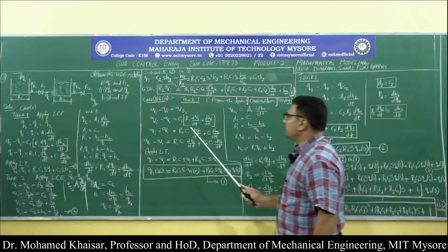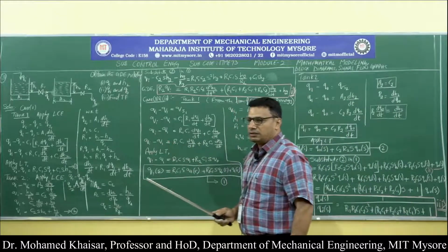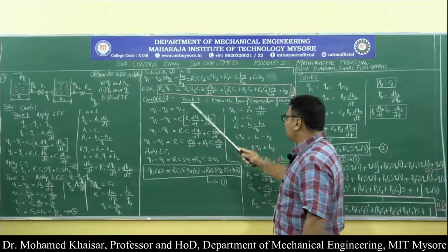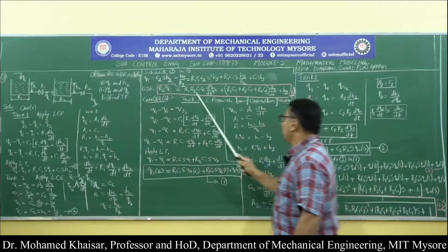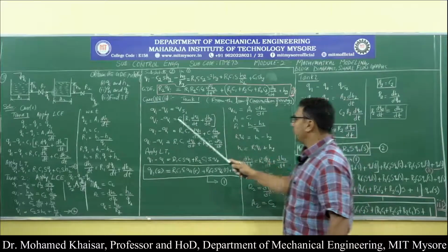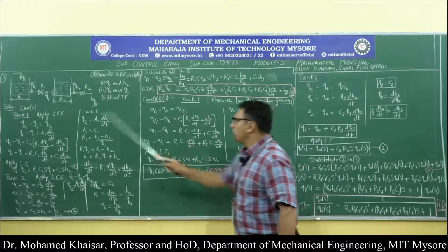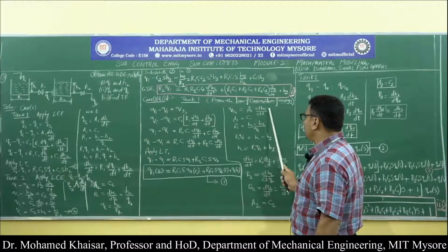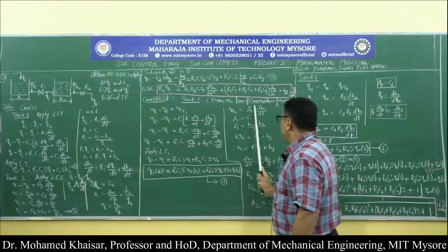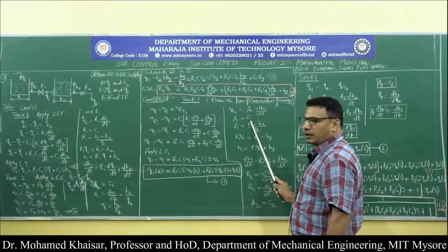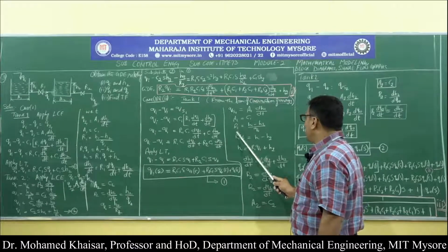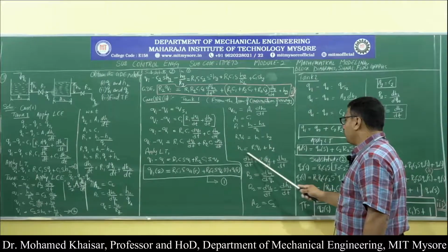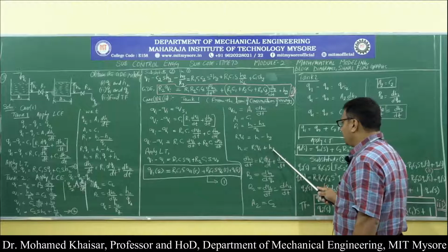Now, if we look at the second sub question, we need to find the governing differential equation in terms of Qi and Q0. See, this is the solution, case 2 and 3. For tank 1, from the law of conservation of energy, Qi minus Q1 is equal to Qs1, as you have known. Qs1 is already known to us, that is, it is A1 into dH1 by dt. A1 is nothing but the hydraulic capacitance C1. Then resistance R1 is H1 minus H2 by Q1, and here R1 Q1 is equal to H1 minus H2. H1 you have found out in terms of Q1 and H2.